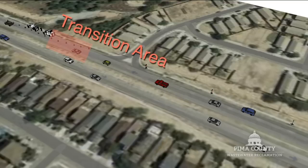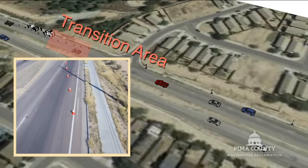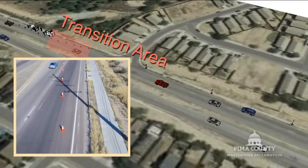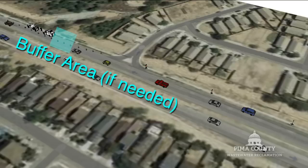The transition area is the redirection of the driver's normal path to a new path. This redirection is intended to occur at the beginning of the transition area. A buffer space is an optional feature for a temporary traffic control near the activity area that separates traffic flow from the work activity or a potentially hazardous area and provides recovery space for an errant vehicle.